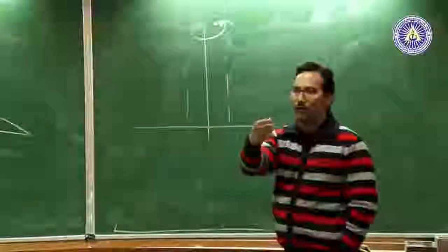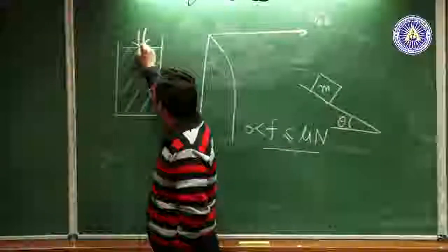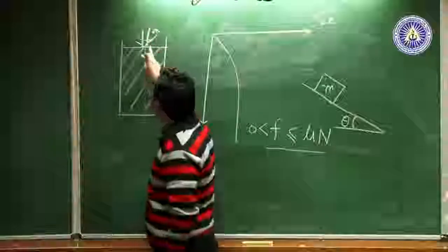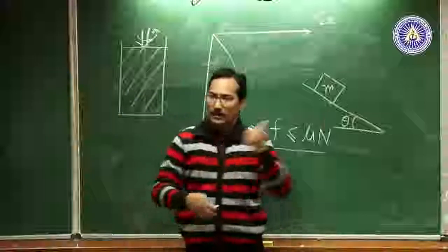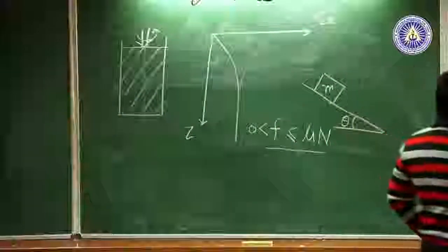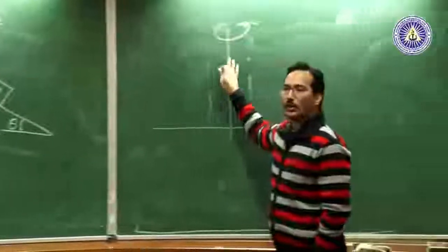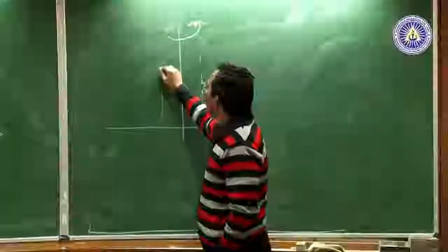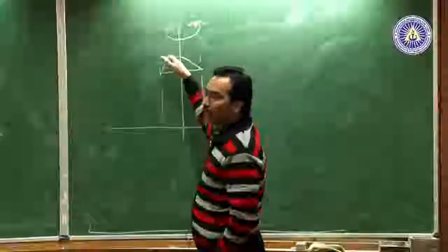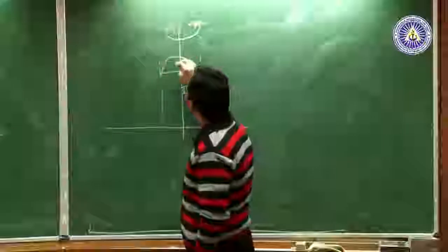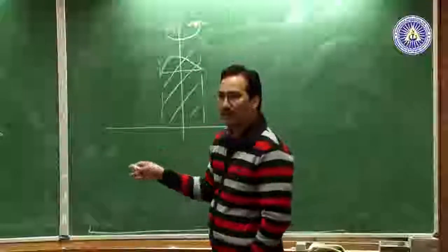So when you solve, you will again assume that friction is fully mobilized. Friction being fully mobilized means that you have to go a minimum distance so that the centrifugal force is balancing the friction force. And so you will see a region in which, depending on what your omega is, your shape is not at all changed, which means I can maintain whatever shape I want here. Of course it cannot go beyond the angle of repose, but there is a region in which you can maintain your initial state given your omega.